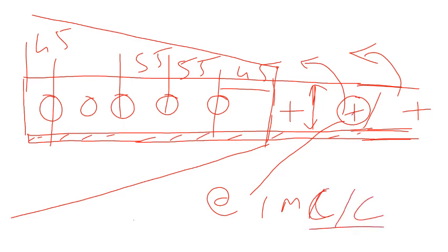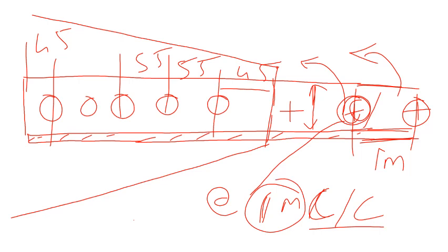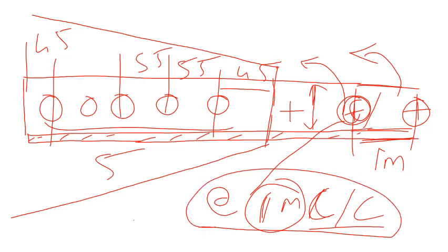So center of this rivet and center of this rivet, this distance should be 1 meter. So depending upon the length, there will be number of tacking rivets and the distance between them will be 1 meter. So this completes our design of the rivet. So we require these 5 rivets and we require this many number of tacking rivets at this distance, and we already determined the size of the ISA, Indian Standard Angles. Also we determined the gross diameter or nominal diameter of the rivets.